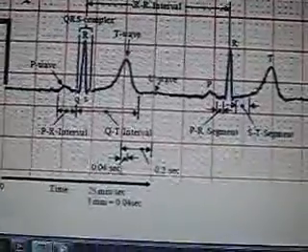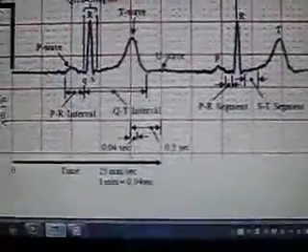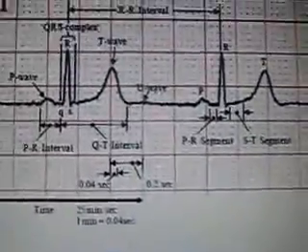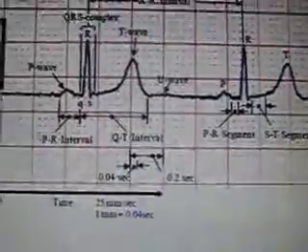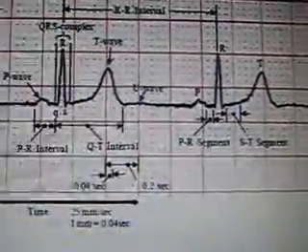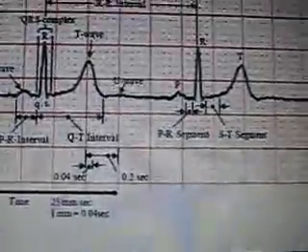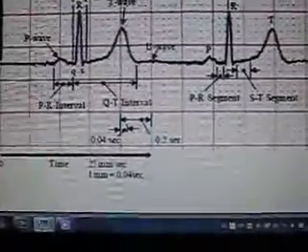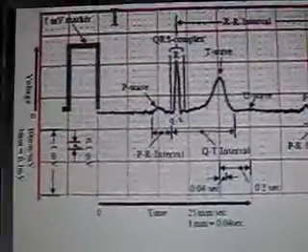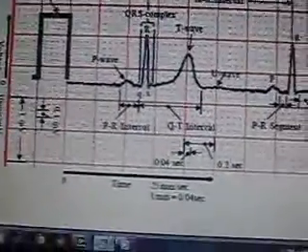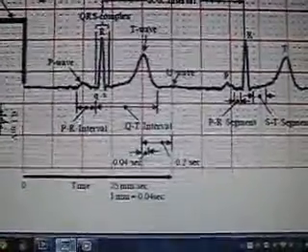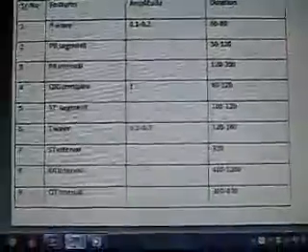And for the normal patient, the time durations of each part of the PQRST waveform, the P wave, PR interval, QRS complex, QT interval, and RR interval, are fixed, and their voltage is also fixed. So if we are able to measure these intervals in abnormal patients and compare these values with the values of the normal patient, we can detect many diseases.